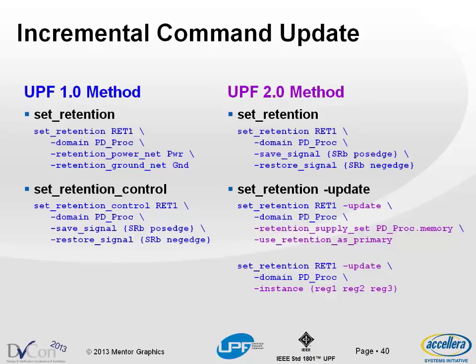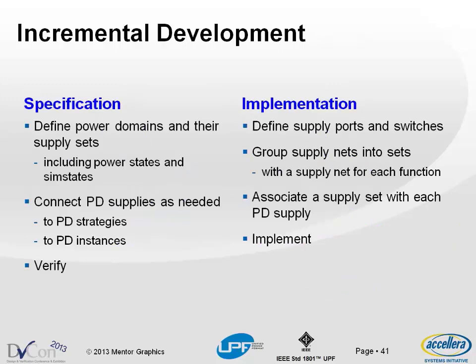In fact, one of the new capabilities is the ability to specify instances that have been inserted into the design to implement part of the UPF. And it's a typical use of model to do that with dash update because you're now into the implementation phase and you're adding more information to the command that was used to drive implementation, but now you're documenting what it did. This incremental development spills over into the methodology discussion.